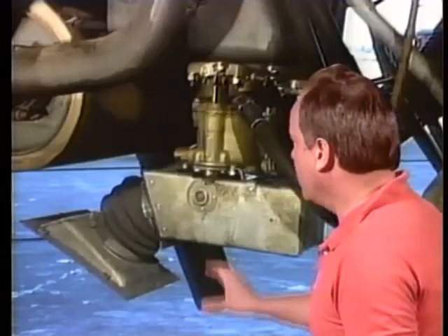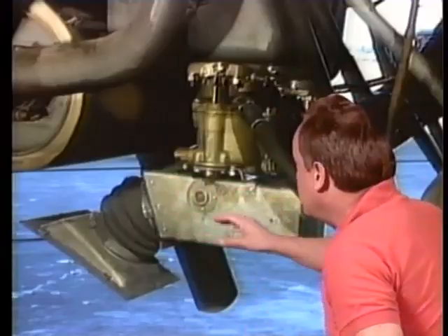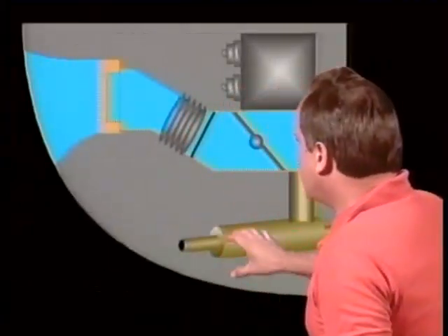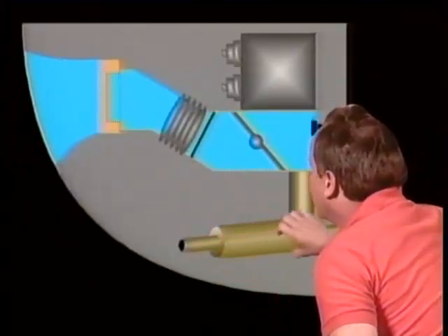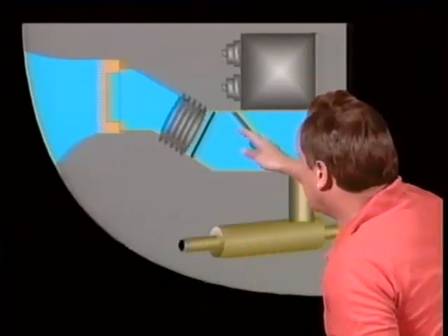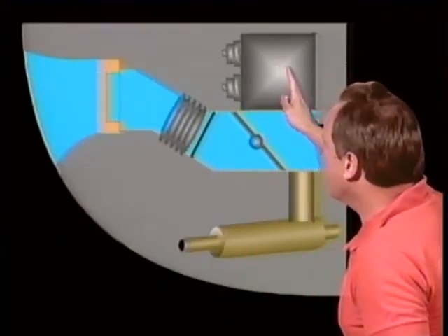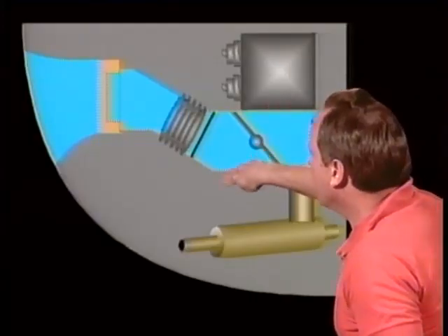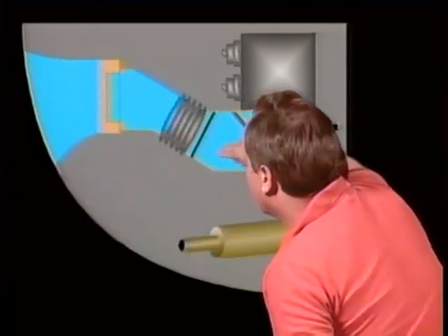They're also going to ask you about the carburetor air intake heater. And here we have one here, and it's basically the heat box, and it heats the air going into the carburetor. If we take a look at our drawing again, we'll get a little better look at that. You can see here we have the exhaust system and a muff around the exhaust system that circulates intake air past this exhaust system without mixing with the exhaust. And when you select carburetor heat, the air gets supplied unfiltered, heated air to the carburetor. On the other hand, if you don't select carburetor heat, then the air that gets supplied to the carburetor goes through this filter, but it's colder air to the carburetor.